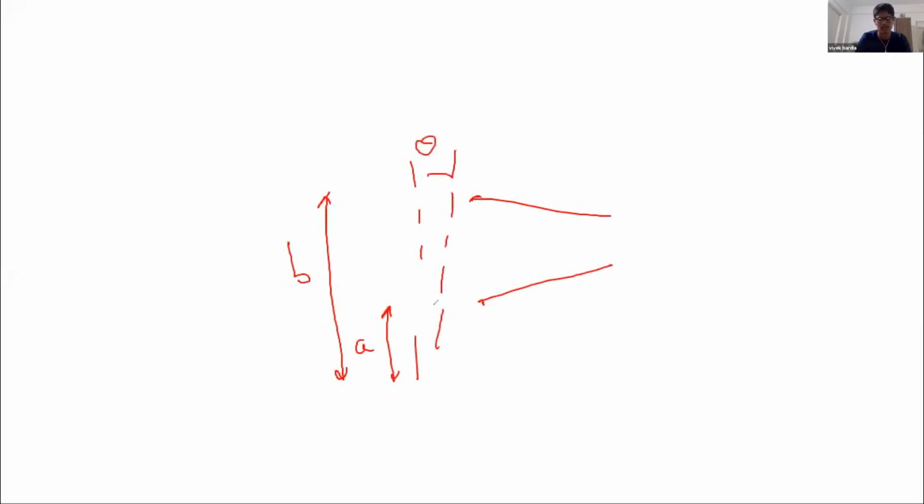So this entire thing can be done on a graph sheet, right? So again, the same thing, we have converging links now. It's rolling again, A and B. It rolls by theta about the roll center, or the RC, right? Again, we approximate that the arc is a straight line. This moves in this direction by B into theta.